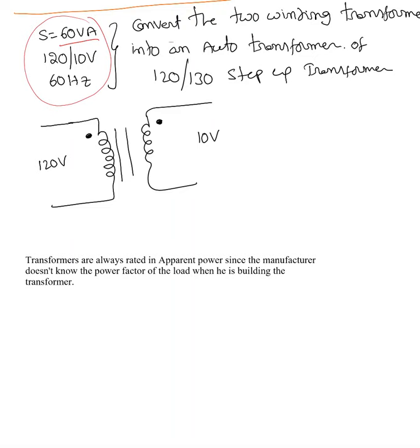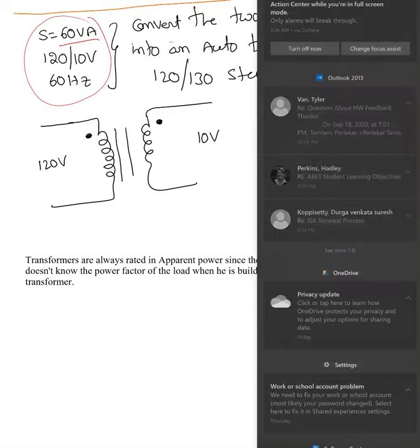Whenever we go to the market to buy a transformer, usually you see these three values: the rating of the transformer, like 100 kVA, 200 kVA, 100 MVA, the voltage rating, like 230 kV by 33.5 kV, something like that, and the frequency, either 50 hertz or 60 hertz.